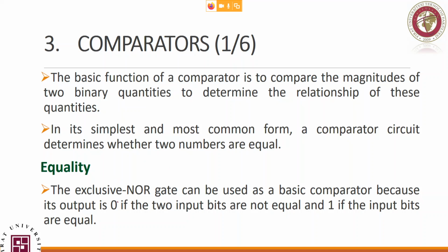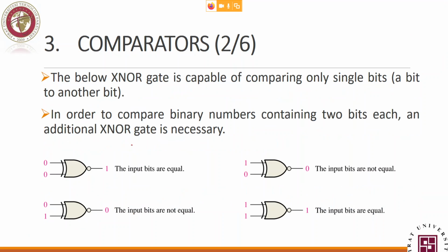Instead of the XOR, you can use XNOR. If you remember, the output of the XNOR is 1 when the quantities are equal. Do you remember the truth table? If you are XNORing A and B, then you will get 1 when they are equal. 0 XNOR 0 is 1, 1 XNOR 1 is 1. In case of dissimilarity, it will give you zeros. That is the way we check equality: an XNOR gate that gives 1 when they are equal, 0 otherwise.